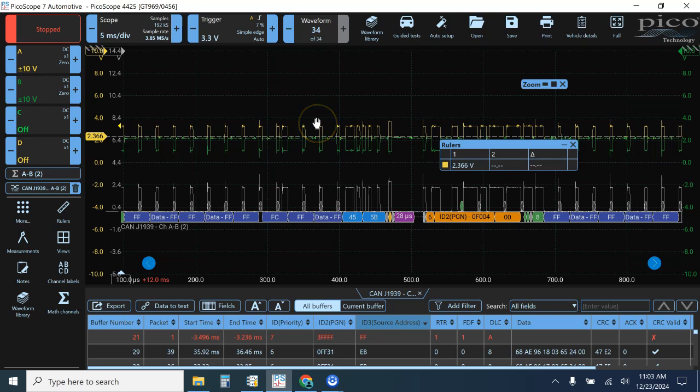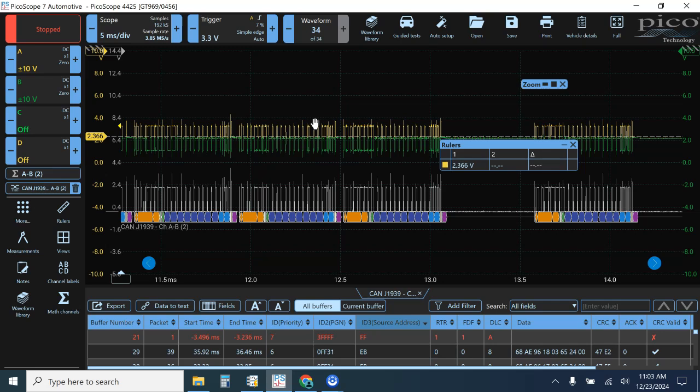Hopefully the diagnostic procedures would have something about checking power and ground, and load testing that power and ground with something that's going to draw similar current to what the knock sensor is going to pull. In that case, I might have condemned the knock sensor as being the problem. It may or may not be. In this case, it just happened to be that I had resistance to ground on that device.